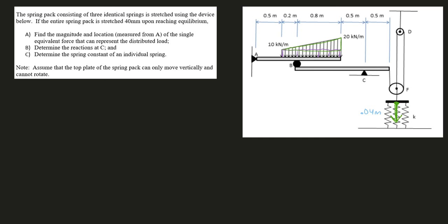For the purple one, because it's a rectangular load, we know that the total force from this rectangular load is right in the middle, and the magnitude of that force is just the area of this rectangle. Its height, a little bit careful here, is 10 times the length, 1 meter. So 10 times 1 is going to be 10, and the units are kilonewtons.